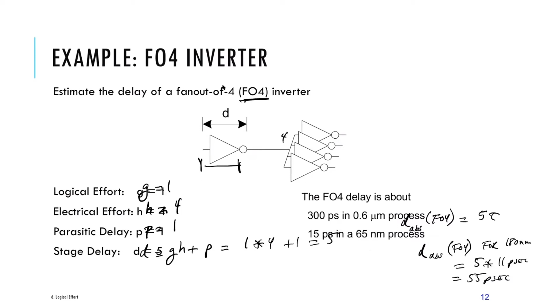Let's just say there are a couple of caveats to using this logical effort methodology. The biggest assumption we're making, and we'll probably see this in our projects, is also the biggest assumption we took in the case where we were using resistors and capacitors. We assumed the input rise and fall time is very fast.